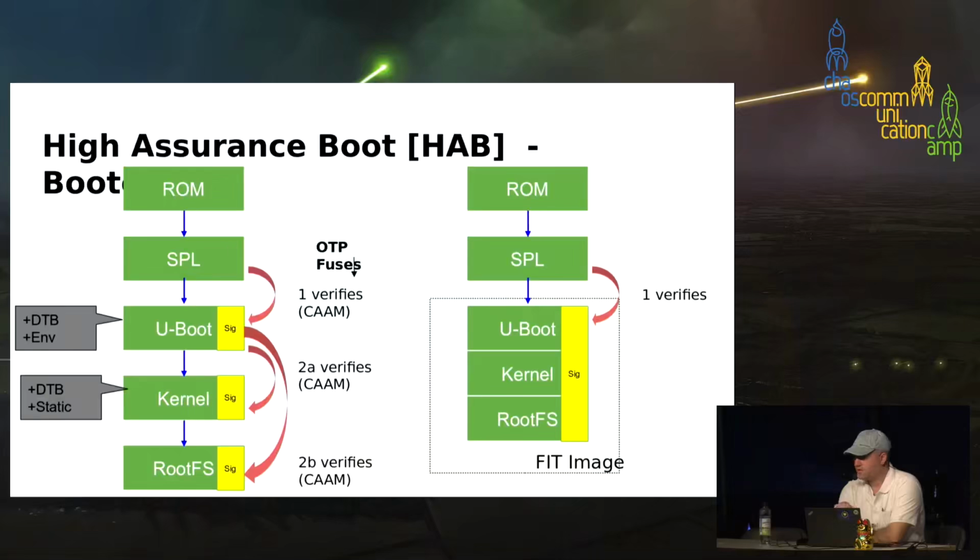Also the device tree of Linux. Usually it's stored externally, on the image. So we want to make sure that nobody is able to modify this device tree. So again, we have to integrate it into U-Boot. The device tree will later be handed over to the kernel, so the kernel will read a verified device tree that nobody was able to modify.